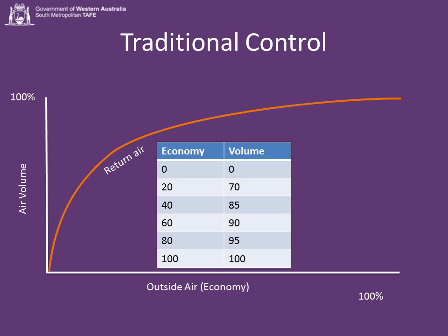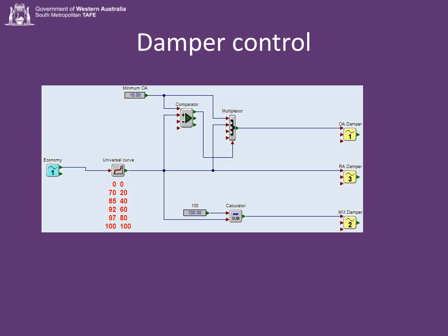through. Now in this one what it's saying is when the actuator is 20% open, 70% of the air volume goes through. So all we do is we program this curve into the computer. And in the computer, if you want 50% air, it doesn't open it 50%, it opens it 10%. And we will actually get correct mixing of return air and outside air.